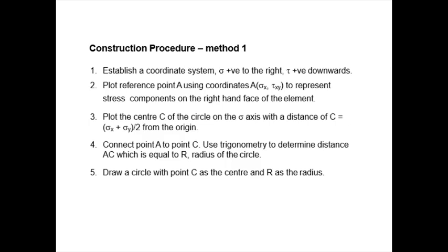So for the horizontal axis or the normal stress, that's not a problem, just put in the center of your graph paper. But for the vertical axis, which represents tau, the shear stress, you have to be careful, because you need to determine whether the graph is going to be on the right of the axis, like our previous example. What we can have is Mohr circle somewhere over there, or somewhere over there, both negative, or everything is negative, or somewhere intersecting the origin. So knowing approximately where your Mohr circle is will help you to determine where you want to place your shear stress axis. Is it in the middle of the graph paper? Is it to the right of the graph paper? Or is it to the left of the graph paper if your circle is on the right?